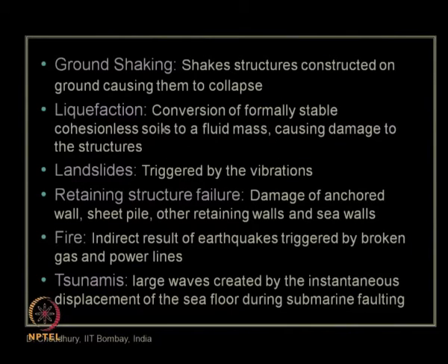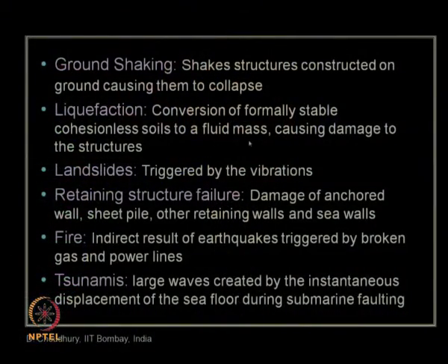As I have mentioned in this sentence, a cohesionless soil, typically below the water table, will start flowing as if it is a fluid or liquid. So, there is no effect of the solid grains which can support the structure or foundation standing on that soil. So, obviously, if during an earthquake the soil gets liquefied, the entire damage of the structure can be expected.